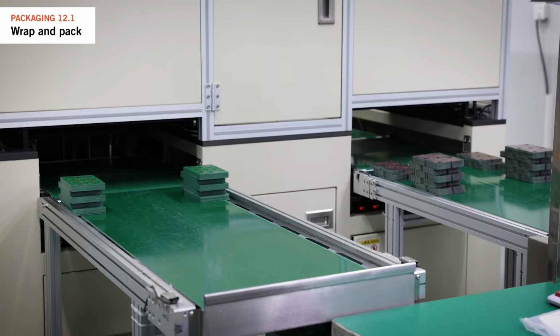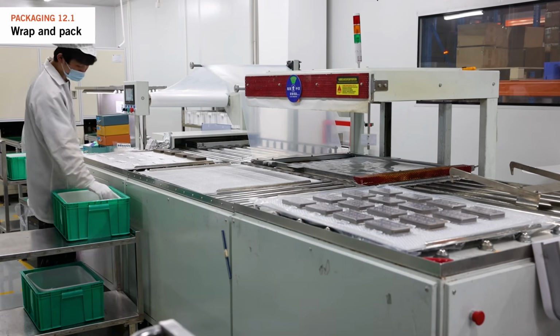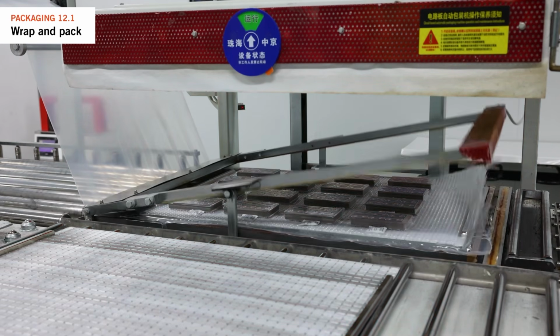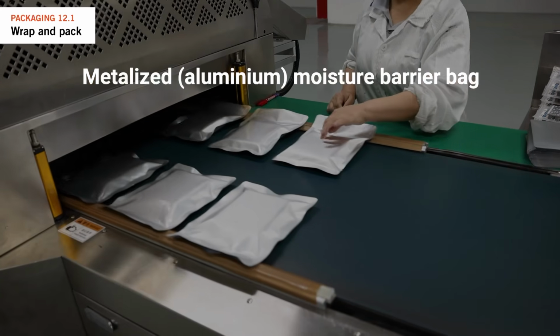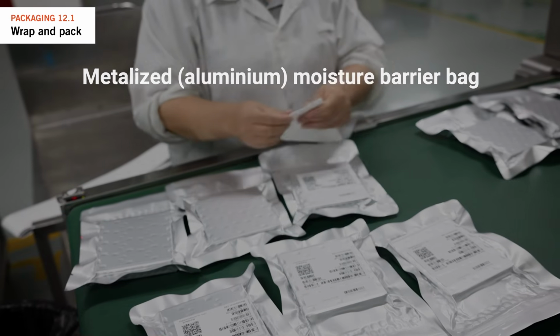Finally, the PCBs are packed. Stacked on a tabletop, a desiccant is added to remove humidity from the shrink-wrapped package. The boards then go into a shrink-wrapping machine to seal the package, creating a soft vacuum by removing most of the air. Some factories also use a silver-colored moisture barrier bag that offers better protection in humid environments.